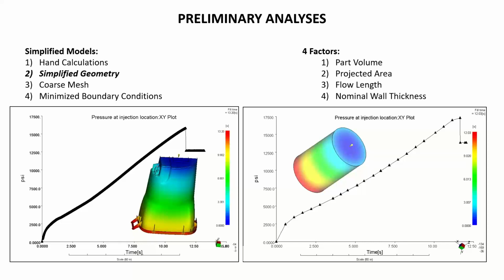Pressure to fill is, of course, guided by the flow length. And the illustration here, it wasn't actually a half model. It was actually a whole model, but it was cut in half for the sake of speeding up the post-processing time. It was officially run with a full model. Anyway, even compared against a half model, it still ran in like a tenth of the time or something like that. I mean, it was like a 10x speed up. It was ridiculously fast.